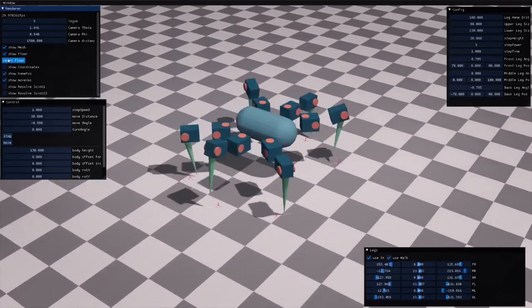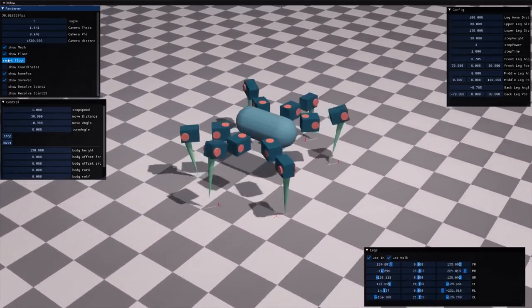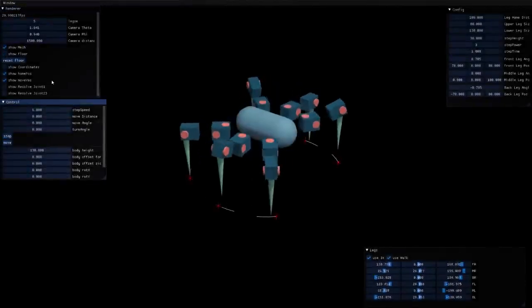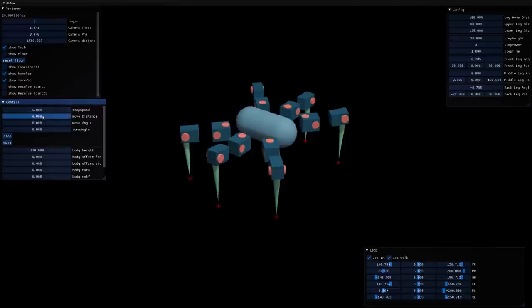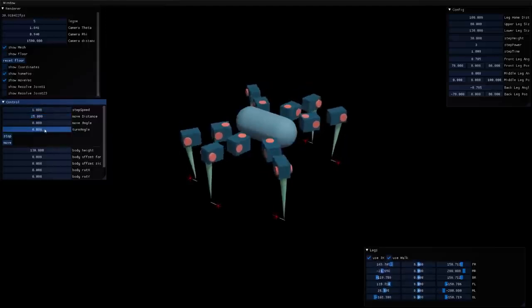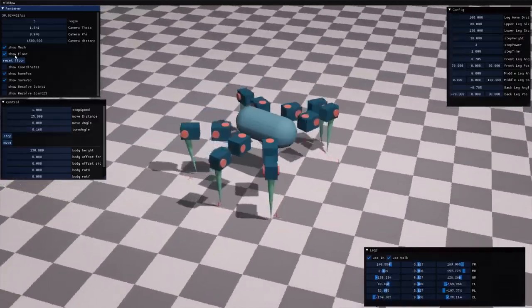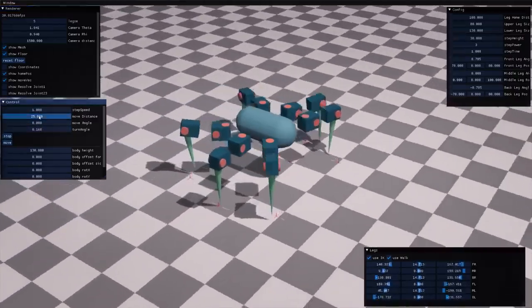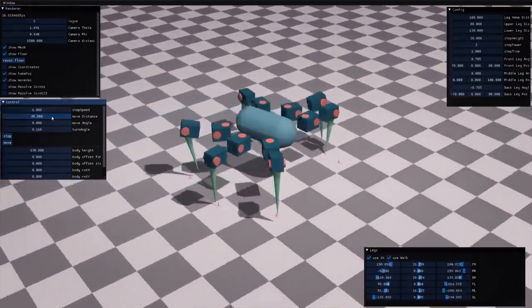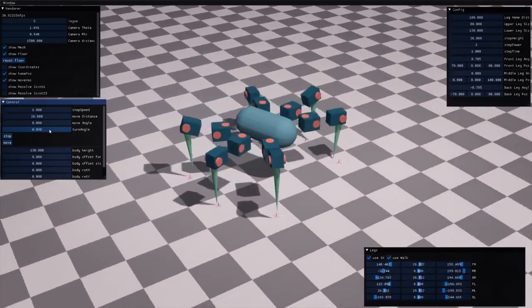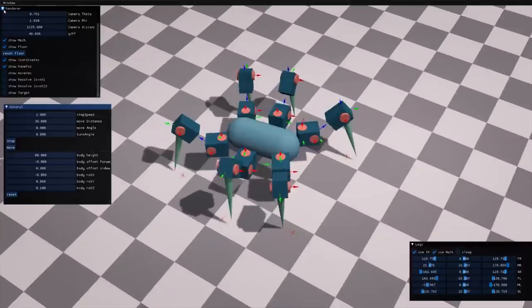For moving in a straight line, you want to follow a vector in that direction, and to rotate, you want to move in concentric circles around the center point. Combining the two was a little bit tricky. I had a small problem that the home position started to drift when I added those 2 vectors. So I made the first part of the step the same as the last part of the previous step. Basically, return home first and then start a new step. I doubt an insect walks this way, but that was a quick fix for now.